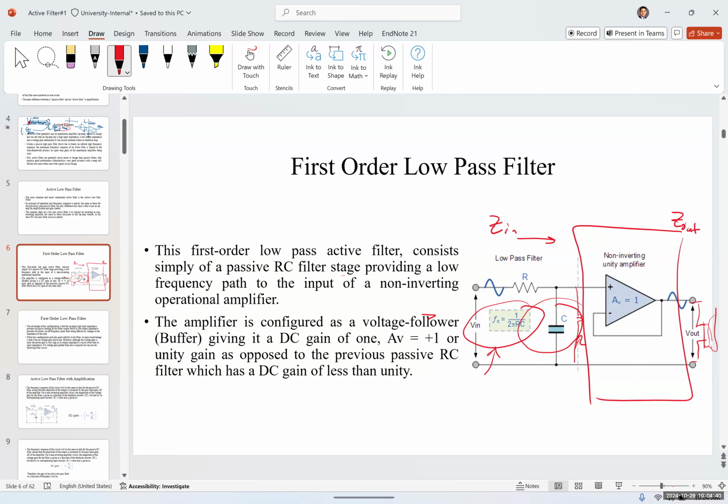And the other thing is that resistor also changes as well when it gets hot. You may have multiple stages of resistors, your potentiometer, and when you change those resistors, the cutoff frequency FC and this R changes. And now suddenly you're just shifting your filter all around the place, and we don't want that. We want this to be fixed at a certain frequency.